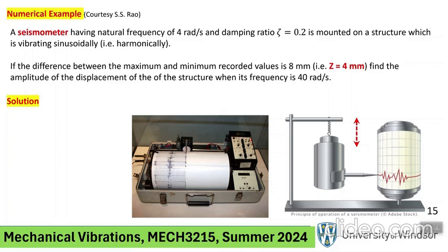Okay. Now, one other thing that I wanted to mention to you is that if you look at the development of seismometer at the first 10 minutes, 15 minutes, we said that it's in the range on the right-hand side where R is very large. And if R is very large, you can think about it as omega n being very small. And if omega n is small, look at the formula for omega n, root of k over m. M is very large. So seismometers have usually large masses.